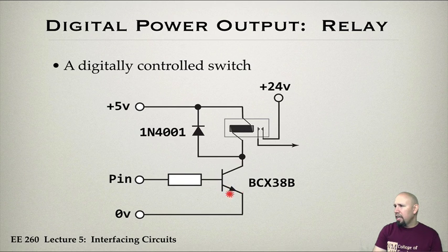And then here is a transistor, or actually I think it's a Darlington transistor, but it's used as a switch. So here this pin is like a switch, which is connected to another switch, which is connected to yet another switch. So there are a number of levels of switching, each one able to handle more current. Basically this one is able to handle more current than the Arduino can handle, and then these contacts over here, this switch basically handles even more current.